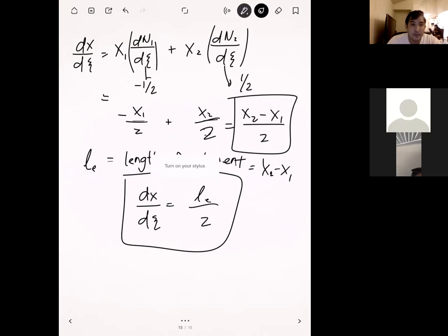Okay, so I used the fixed one, but I was wondering why it's a fixed support. That's why I wanted to know. I think the better answer is that we needed to constrain this in a way that we could solve it. It's definitely a much simpler version than what a bike crank is in reality. In reality, I think you're right, it is closer to a pin support, but because we're looking at a simplified version of it, we have to make it a fixed support just so that we can solve it.